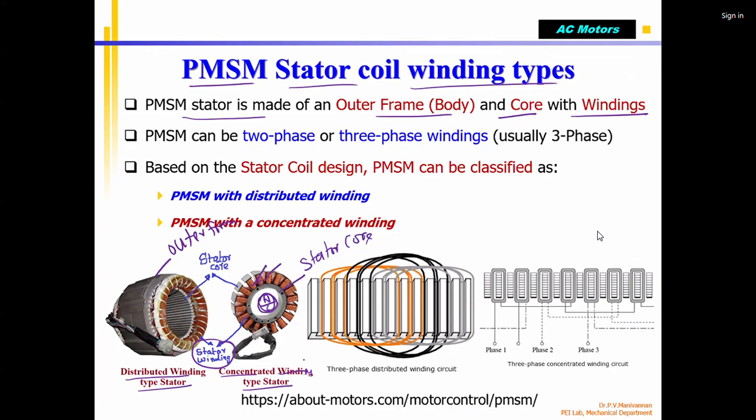Again, it is a three-phase winding only. Please note that this is a three-phase winding. And in this case, the coil is distributed evenly. There's no gap. You can see that this is one coil. The white color is nothing but the insulation in between. The brown color is the copper coil. There are three-phase coils wound through slots.